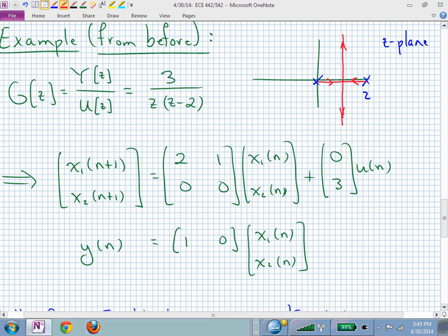So the best you can do is for it to be marginally stable, and I wouldn't like that at all. I wouldn't want to be right at 2 poles at z equal 1. That's a bad system to be trying to live with. You just bump it with a constant and it's going to go crazy. It's actually unstable if I have 2 poles right there at z equal 1. Can't even hope that this be marginal. Because now if you have any kind of an initial condition, it's going to go unbounded.